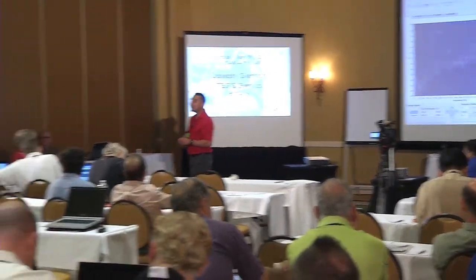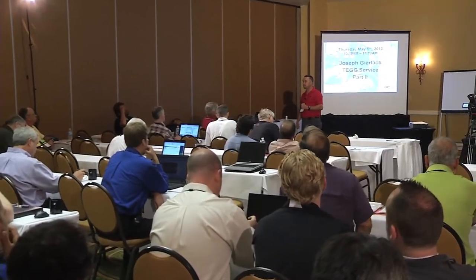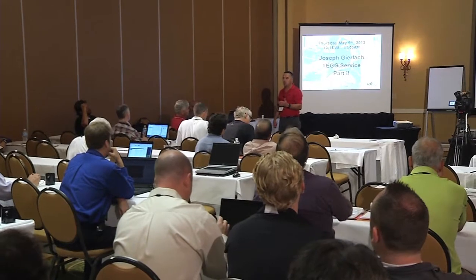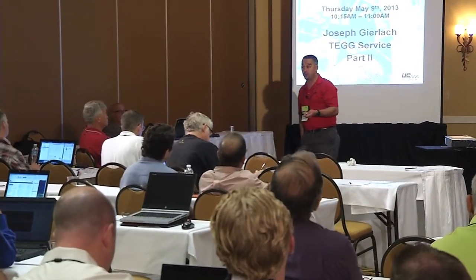Yes, sir. Explain that one more time, how you really differentiate between the mechanical and the... All I said was if I see a frequency peak in the FFT that's 1/2 my operating frequency, I know immediately it's not an electrical fault. And it's because you're not going to see things like arcing, tracking, corona, destructive corona produce or generate a 30 or a 25 hertz harmonic. It's just not going to happen on the electrical side. But on the mechanical side, it will.